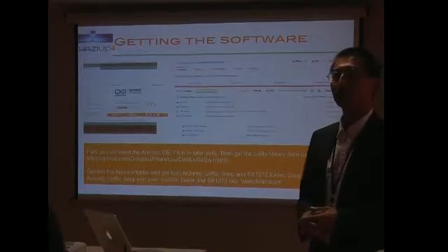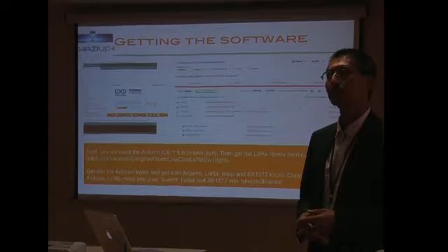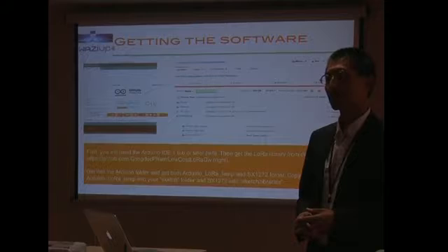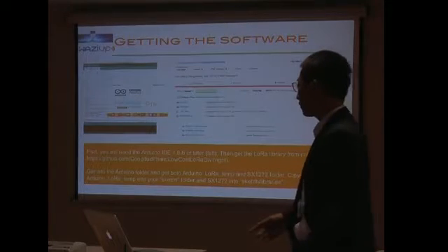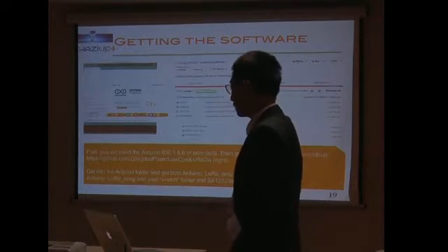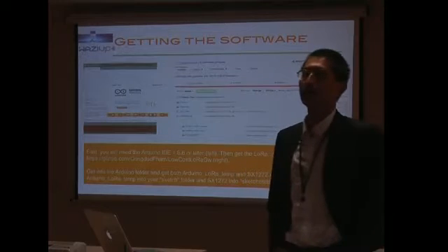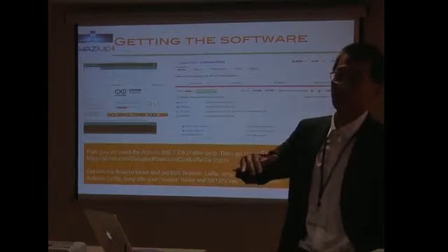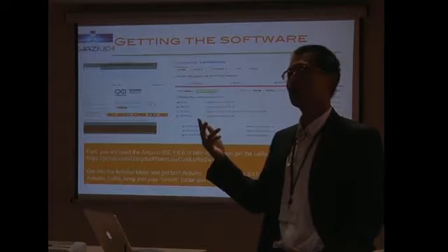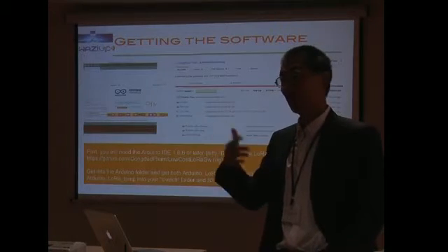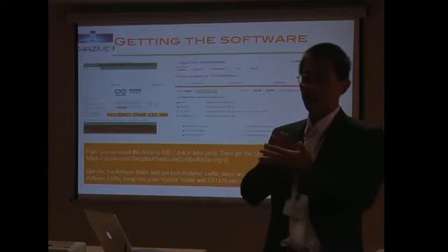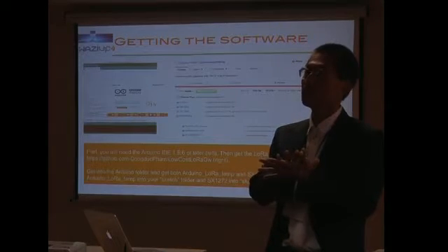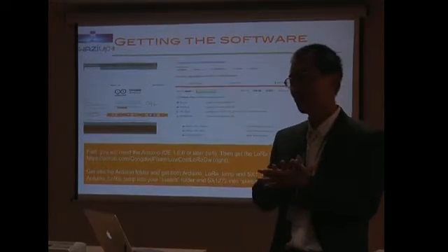More questions? Which radio frequency do you use for the long distance transmission? So most of these long-range radio technologies are working on the sub-gigahertz, which means below 1 gigahertz. We have an unlicensed spectrum in France, in Europe mostly, at 433 megahertz.